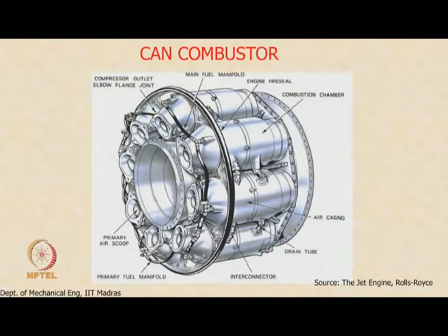So, they all operate more or less at the same pressure, pressures are equalized by the interconnecting tube. You can see that the compressed air comes from this side. This end connects to the compressed air, and you can see the space for the shaft to go through. This is the inner casing, the shaft goes through this passage. This side connects to the turbine, so the hot gases from here directly flow into the turbine blade. This side connects to the compressor.